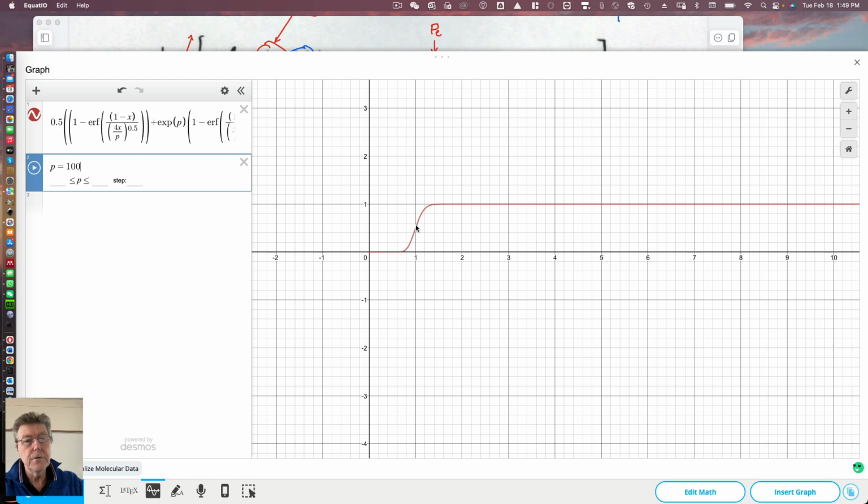When one pore volume breaks through, it breaks through at 50% concentration. Already earlier than that, it's broken through at a lower concentration because of diffusion about the front. It goes past because some of that concentration has arrived ahead of the front, and some of it behind the front is depleted.